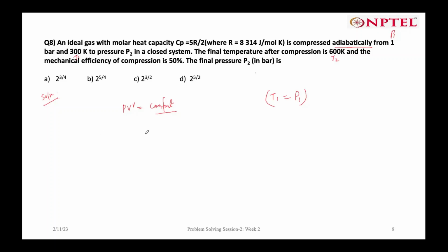So we derive, like, P2 over P1 is equal to, with T2 over T1 raised to gamma over gamma minus 1. Answer is D, sir. Yes, right. Basically in GATE, generally questions are asked based on the adiabatic process, so we have to derive some relations. All of you got the same one? Yes, sir. Okay.